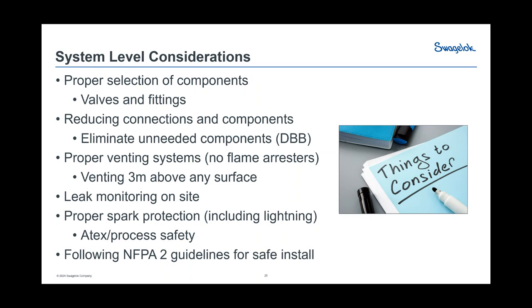But the one issue is, in many cases, one of the devices we have on hydrogen systems is thermal pressure relief devices designed to release the pressure if there's a thermal event. So you want to empty that system as quick as possible because storage tanks can't handle what's going to end up being a large pressure rise coming from a thermal event near it. So you want to vent quickly. So no flame arresters in those systems, and be careful to make sure those are sized properly.